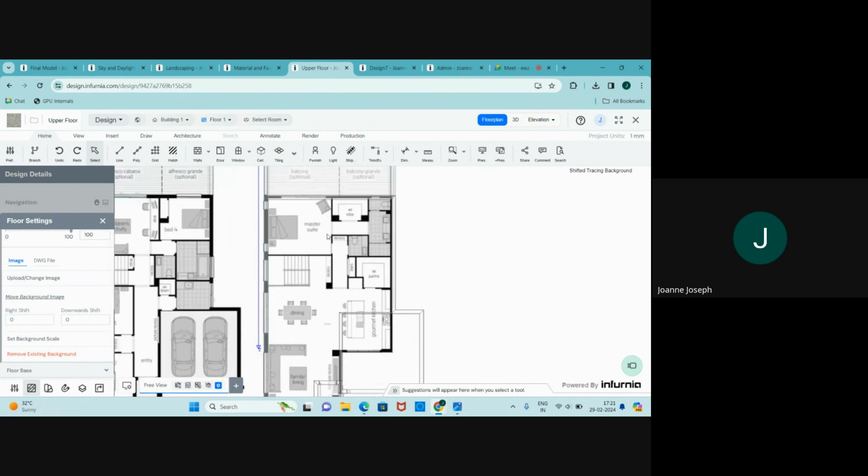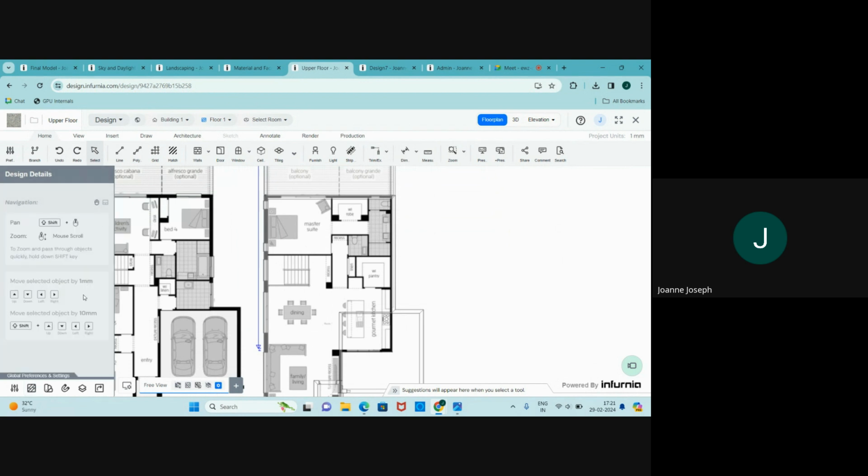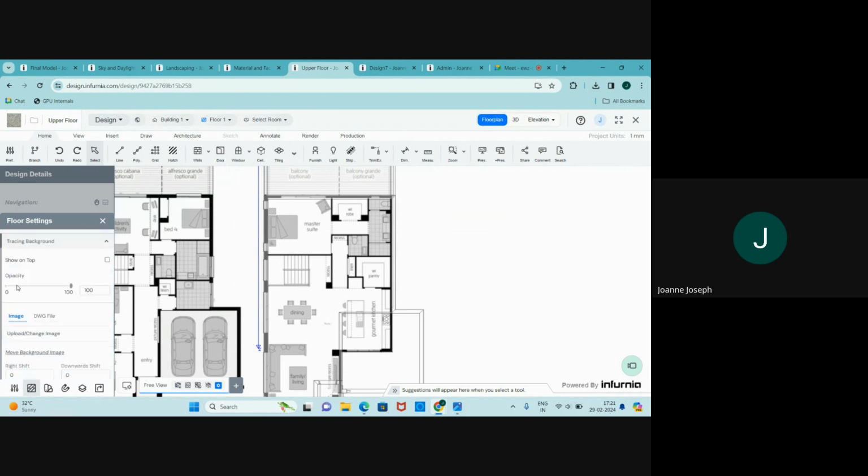So now we can proceed with drawing the walls of the first floor. And we can even set the floor level limits of this particular floor now by going to floor settings, scrolling up. And as you can see, the bottom is now starting from 3,000 above the ground level. And the top limit is 6,000. We can even play with the heights and change it to something like 8,000.